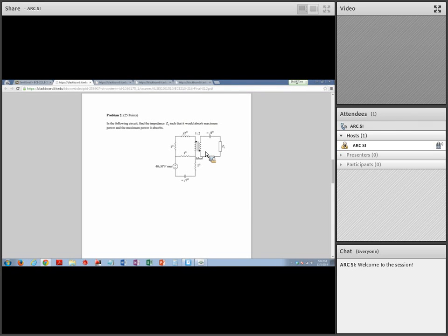These dots might be flipped. The plus and minus are always on the same side. I don't know if I'm understanding what you're saying correctly. But no, this is fine when the dots are on opposite sides and you have V1 with the pluses on the same side. One will be the negative of the other times the turns ratio. And that's what you had here.